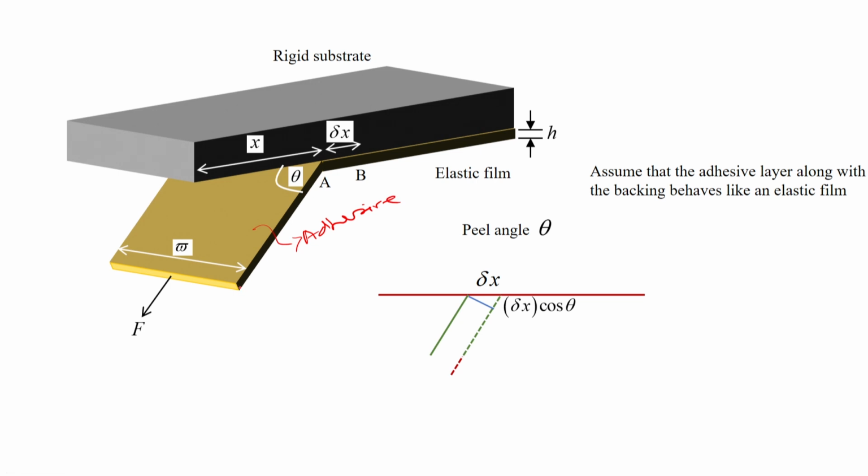It remains bonded to a backing. Part of it is backing also. The backing does not stretch and does not take up any energy; that is the basic assumption here, although it does not necessarily have to happen that way. Now we apply this load, and because of that, over a very small infinitesimal amount, delta x, this adhesive comes out of contact with the substrate.